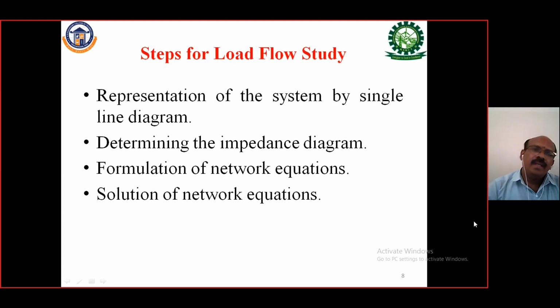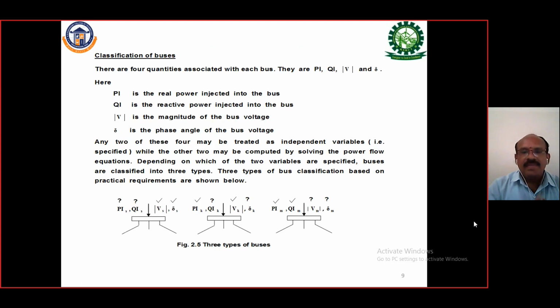Steps for a load flow study: a representation of the system by a single line diagram. In any power system, first we should know how to draw the single line diagram. From this single line diagram, we have to obtain the impedance diagram. Next, we should know how to calculate the Y bus matrix and Z bus matrix. Then the solution of the network equations, the load flow equations. In the next class, I will plan and teach the power flow equation.